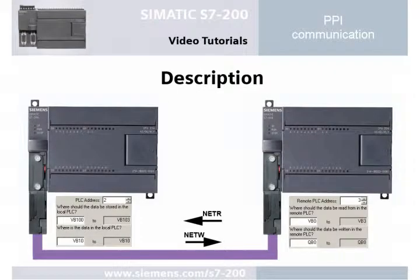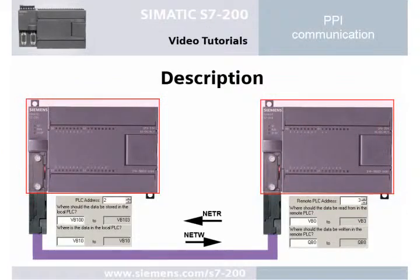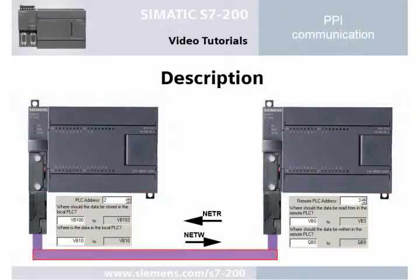Welcome to the SIMATIC S7-200 video tutorial for point-to-point communication. Using the function blocks Network Read, NetR, and Network Write, NetW, up to 16 bytes of data can be exchanged between S7-200 PLCs via the PROFIBUS cable. The respective communication partner is identified by the address.